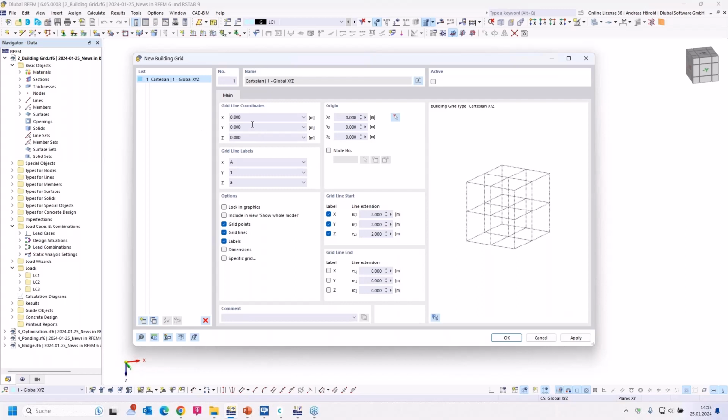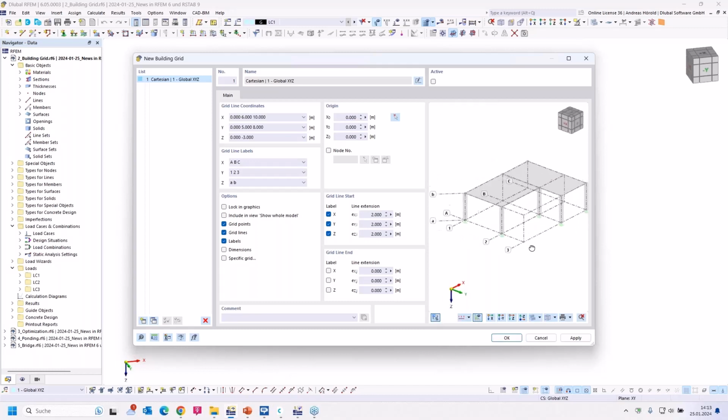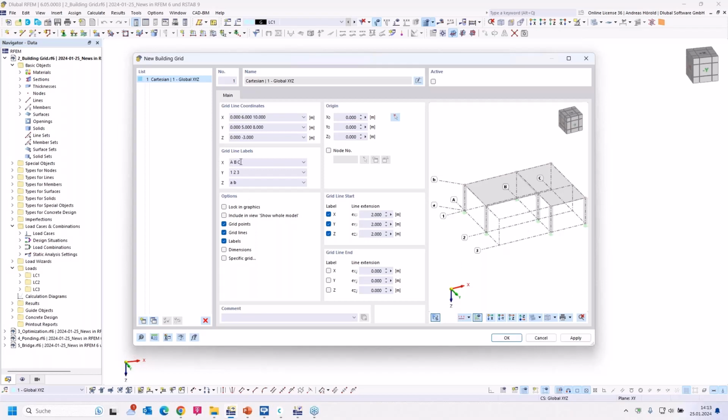So that's the menu. Yeah, you need to enter the dimensions of the grid. Usually they are known, with a space between the numbers. And 0 and -3. Okay. And you can already show that in the preview. When I press this button, I can see if it's correct. You can enter here numbers also if you want, rows and axes. I leave them as they are.